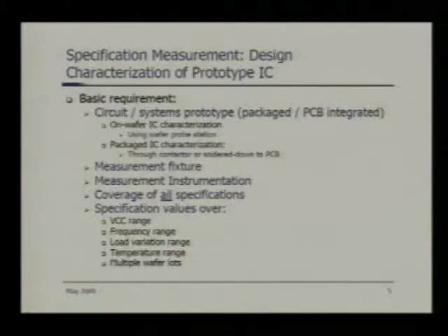Not only that, for RF circuitry, we have to cover for the load variation. For example, if the amplifier is specified for 50 ohm, and the load varies from 55 ohm to 45 ohm, will the gain distort or change drastically, or does it stay almost close to the typical value?